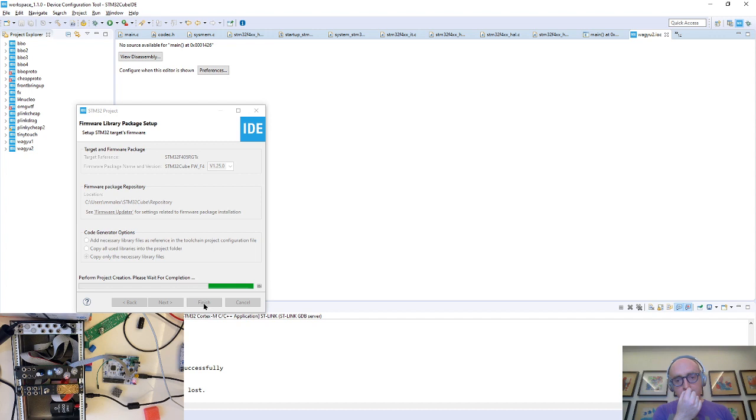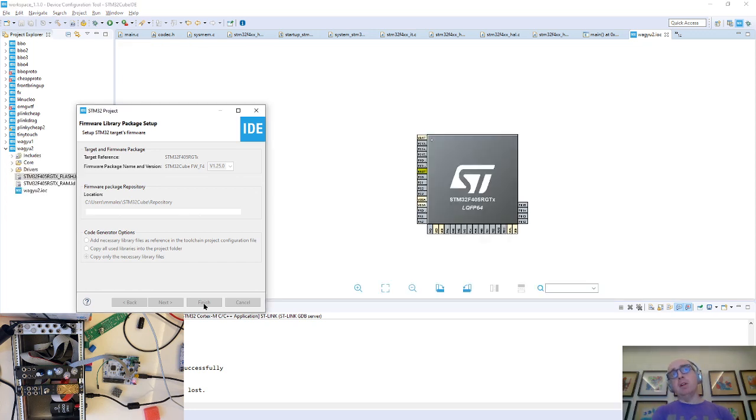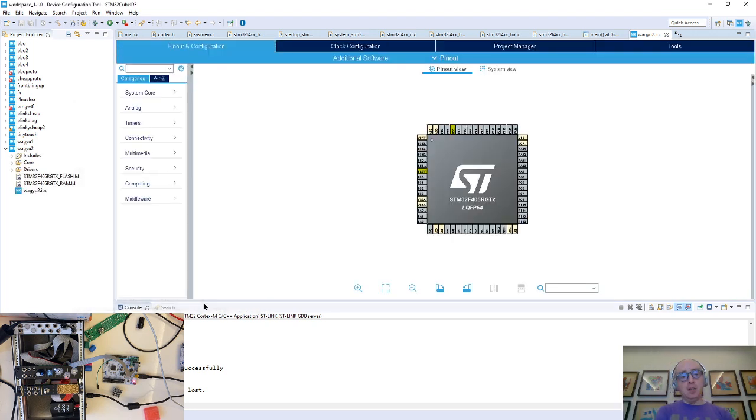I have a hard time understanding how to program the ST Nucleo though. Yeah, so program the Nucleo itself. Basically, if you've got a Nucleo, all you need to do is plug in a USB cable, go into STM32CubeIDE, as I'm doing now, go to the board selector and select the Nucleo board, and everything should just work. It may complain about firmware updating, so you need to do the firmware update.